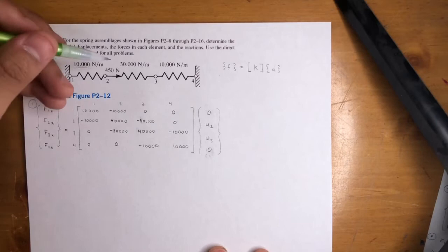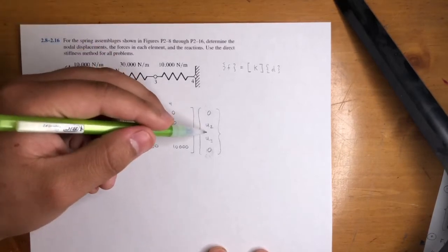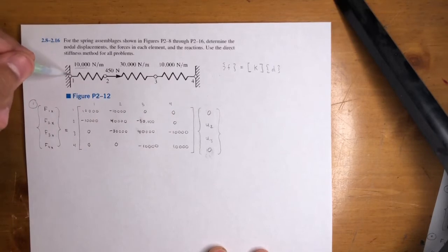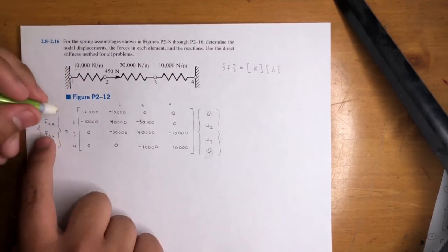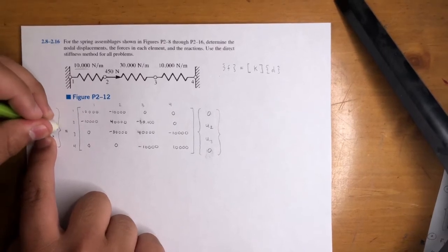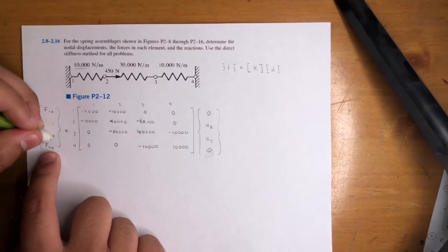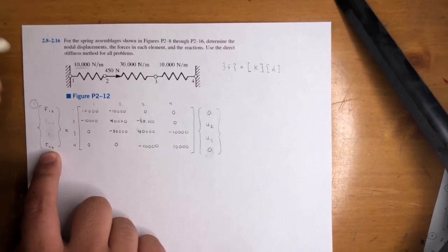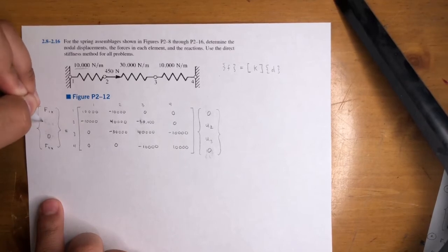And then obviously if you apply force here, 2 and 3 are going to move. So we're looking for these two. If you apply a force at 2, it's a positive 450. So we got that one. There's no force at 3, right? There's nothing going on at 3. It's kind of just moving with the flow. So that's going to be 0 and positive 450 at node 2.